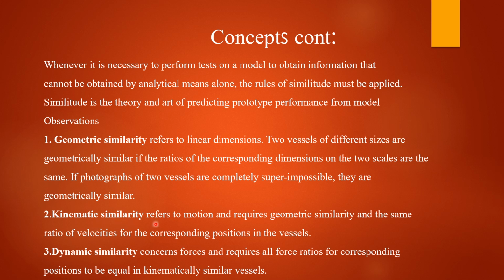Kinematic similarity refers to motion and requires geometric similarity and the same ratio of velocities for the corresponding positions in the vessels. Dynamic similarity concerns forces and requires all force ratios for corresponding positions to be equal in kinematically similar vessels.